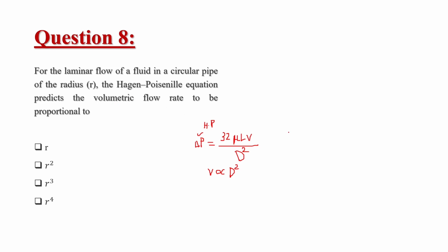So this term a is not equal to 0, because if a is equal to 0, then u will always be equal to 0, which is not feasible, and in such a case there would be no velocity profile at all. So a is a non-zero term. So h minus 2y should be equal to 0, that means y should be equal to h by 2. So we can get the maximum velocity at y equal to h by 2.